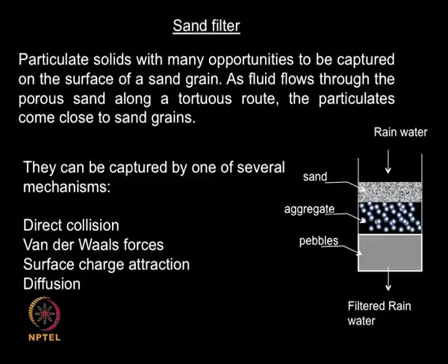You do not need to spend any money on chemicals or on utilities and services, and mostly they operate under gravity. You feed the liquid or water from the top, and because of gravity it flows down, and then flows downstream to various points in the plant. So that is the main advantage of these depth filters.